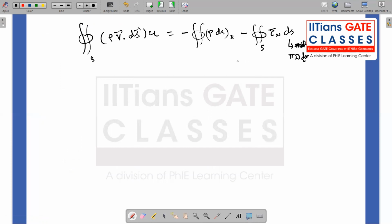Okay, so this part I can write in terms of rho 1 u1 square A. The same thing we did earlier, so I am not going to give you the details. A is constant, so I am just treating it as A, plus rho 2 u2 square A is equal to the integral of tau dS in x.